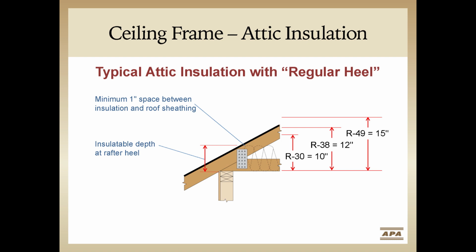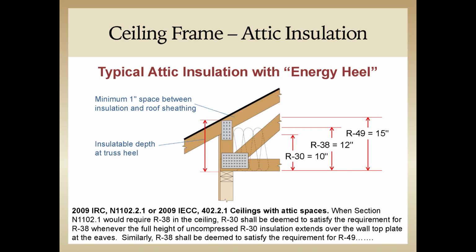So far, we've only discussed what insulation installers need to know about wall insulation, but let's take a look at roof insulation as well. When a standard truss is used, the ceiling insulation is compressed over the wall top plates, as shown in this detail. On the other hand, if we look at a raised heel truss, you can see that the heel allows for the insulation to remain uncompressed over the wall top plates.